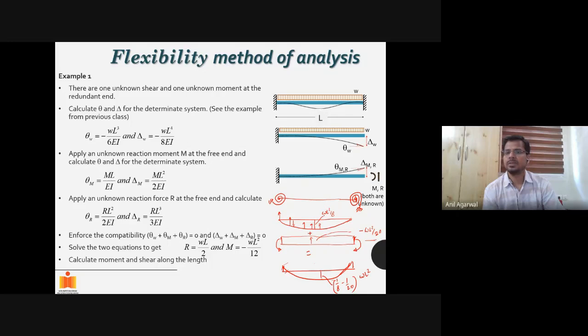Okay, so if it is a fixed beam, let's say you are planning it to be a fixed beam, your moment demands were here. How much was the moment demand if it was a fixed beam? Okay, in negative, and the moment demand here would be WL square by 12, sorry, 24. Now, typically what happens is that, especially in steel, you can often go with a symmetric section, right? So its positive bending moment capacity is very similar to its negative bending moment capacity.